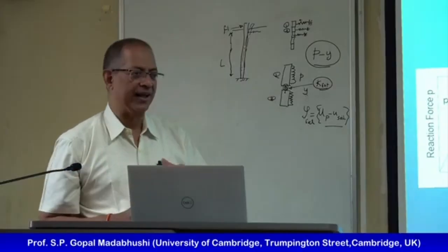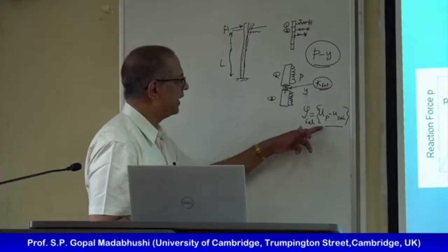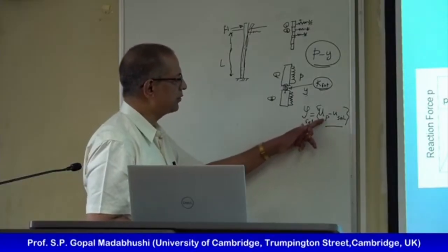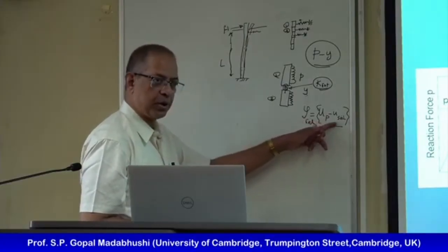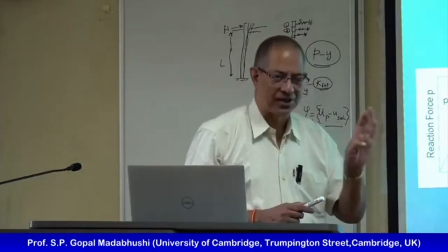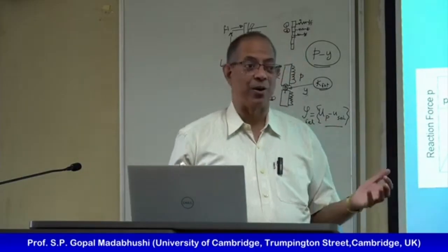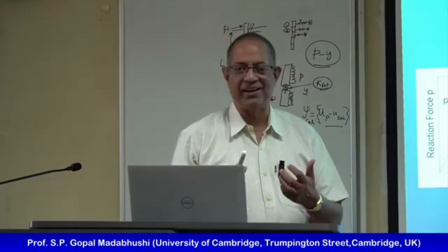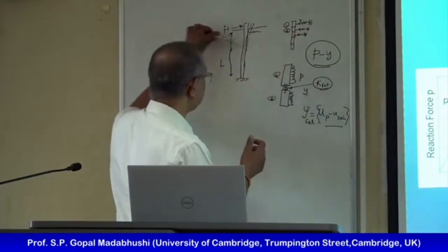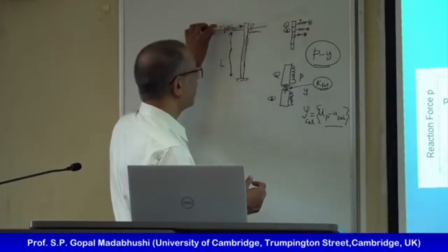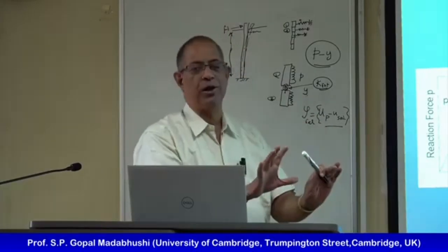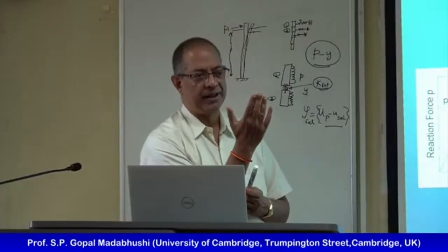The only thing here is we may get this deflection of the pile and deflection of the soil. If my soil is moving down the slope, then that's going to be a lot bigger than what the pile can do. So if my soil is coming and attacking the pile this way, it's not that I'm applying a horizontal load, but I'm applying a big soil pressure that's causing my pile to bend.